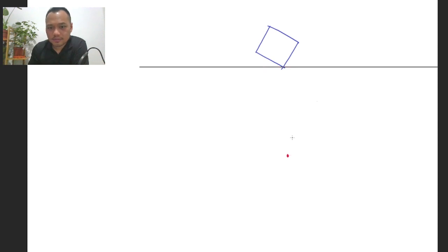So now we have our station point, we have our floor plan, we have our picture plane line. What we're going to do next is make a floor line or a ground line. We usually put this beneath the standing point line. So this is our typical setup. We'll have the floor plan way on top, above the picture frame line, and then our standing point will be between the ground line and the picture frame line, right?